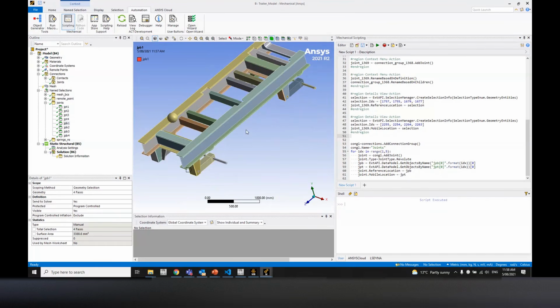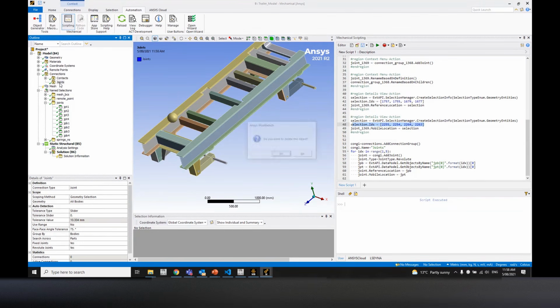Now I've got everything under name selection, so I can pick it up easily instead of doing reference IDs, which is just a waste of time, and you don't know it's 2255, right? Again, not interested. So that's why we go through name selection. So what I did is something a little bit fancy here. I'll just show what I did as well.